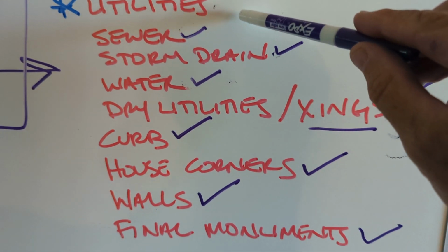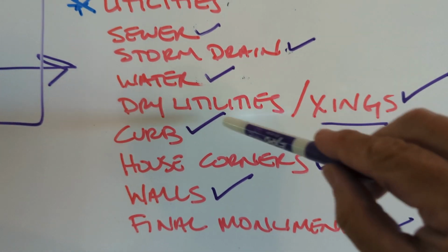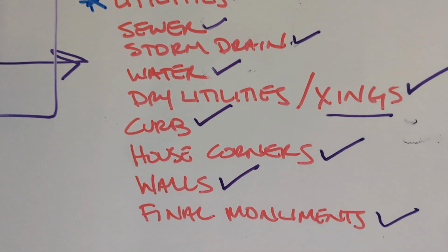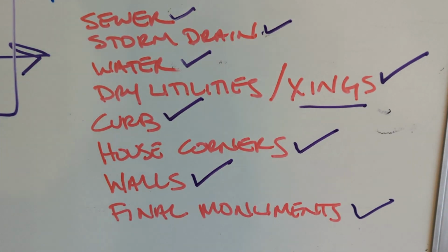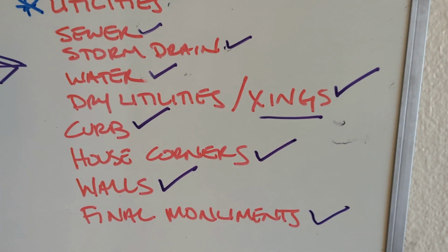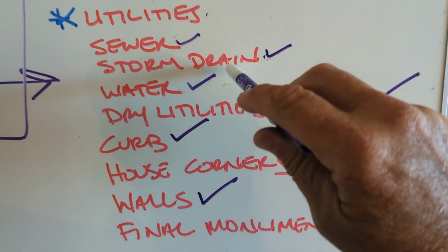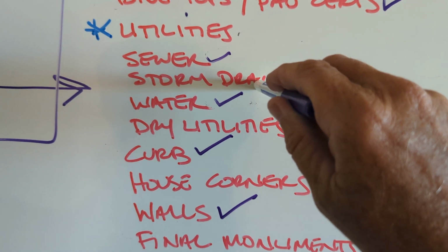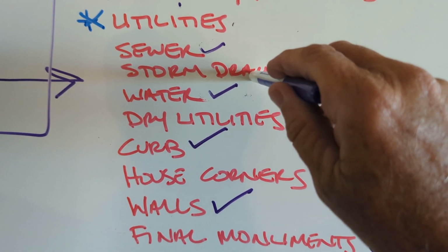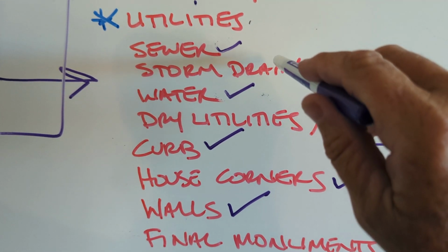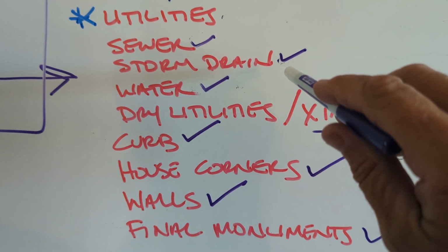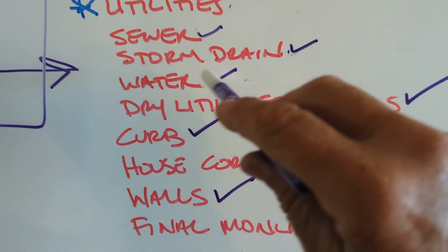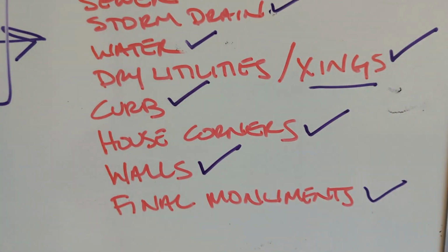Utilities, underground utilities, you have more leeway. We stake out. I mean, we stake out everything. We don't set up on something and just pull a chain and scratch and give line. So even though a lot of this stuff could be plus or minus a tenth horizontally, we probably stake it out within a few hundredths. But grade is more important in my opinion than horizontal. If you're talking just a couple hundredths, grade is how that flow is going to work.